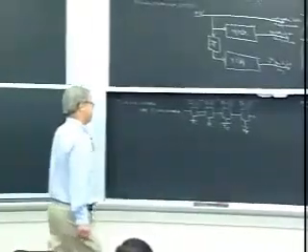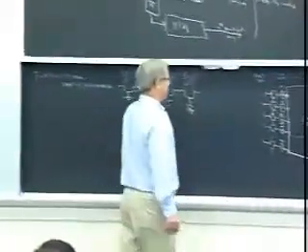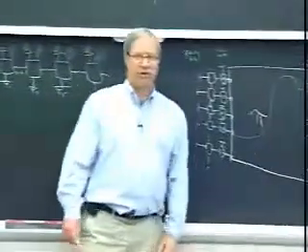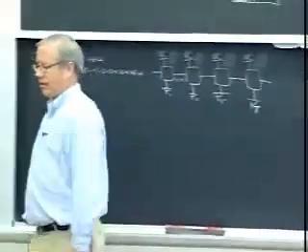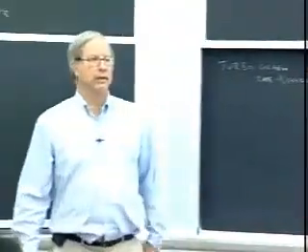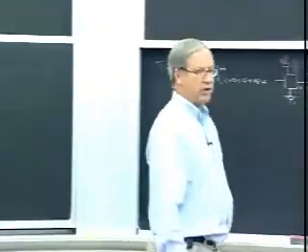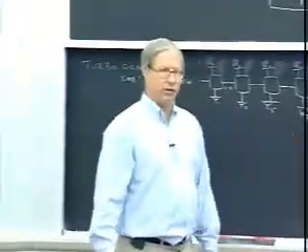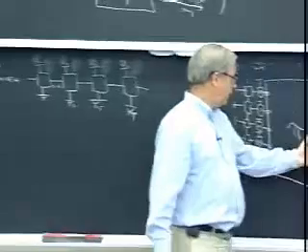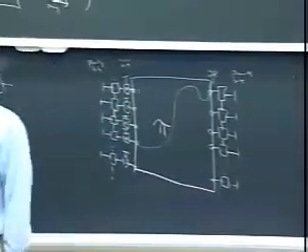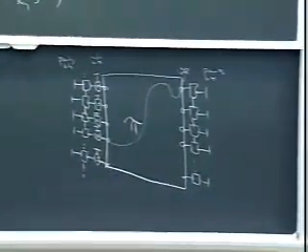It's a quaint but apt analogy. All right, so this is the normal graph of a turbo code. And you see I've drawn it to emphasize its commonality with low-density parity check codes. The biggest element is this big interleaver in here, and that's the key to the thing working well.